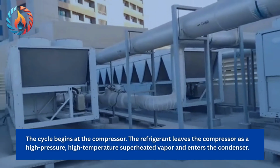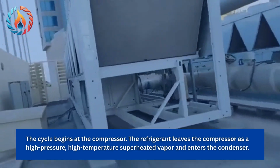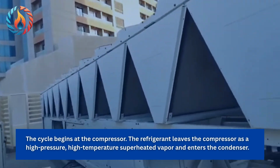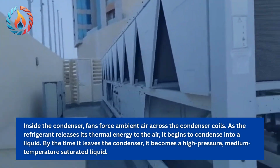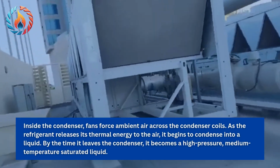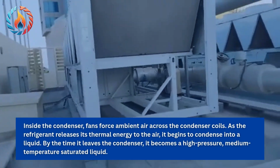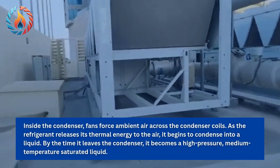The cycle begins at the compressor. The refrigerant leaves the compressor as a high-pressure, high-temperature superheated vapor and enters the condenser. Inside the condenser, fans force ambient air across the condenser coils. As the refrigerant releases its thermal energy to the air, it begins to condense into a liquid. By the time it leaves the condenser, it becomes a high-pressure, medium-temperature saturated liquid.